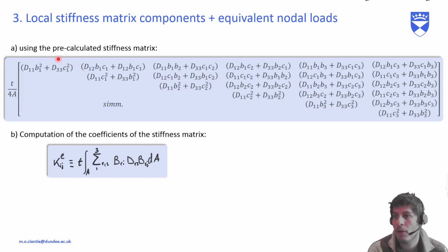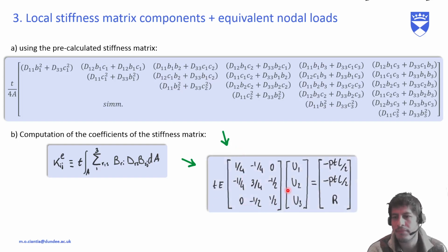So basically, if you want K1 of the element, you compute this. But look back at the previous class where I also report the terms B1, C1, etc. Independent of the approach you want to use, we can then write our system using the element stiffness matrix values just calculated.